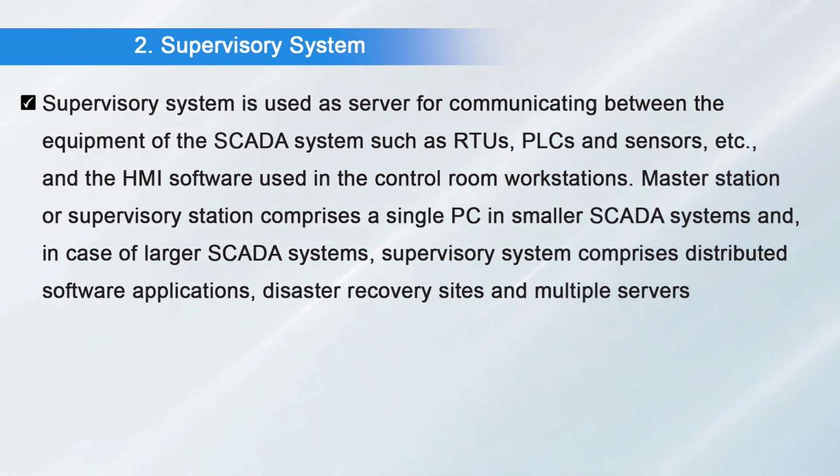In the case of a larger SCADA system, the supervisory system consists of distributed software applications, disaster recovery sites and multiple servers. These multiple servers in the larger SCADA systems are configured in a hot standby formation or dual redundant, which continuously controls and monitors in case of a server failure, increasing the integrity of the industrial system.